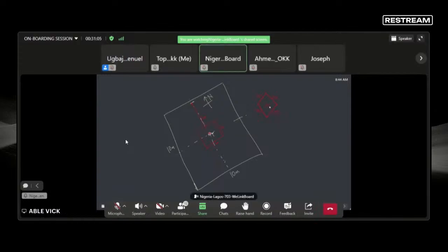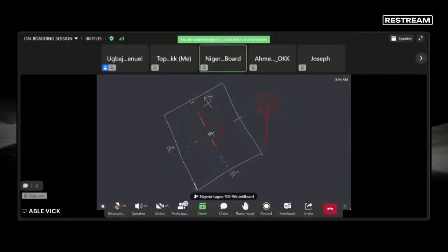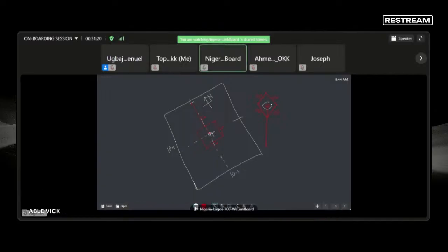It is the anchor plate here that connects the iron rod. So your guide wire base plate is like this, 750 by 750. Your 5 meters is stopping at the center of the base plate, not at the tip of that base plate. This one is wrong.